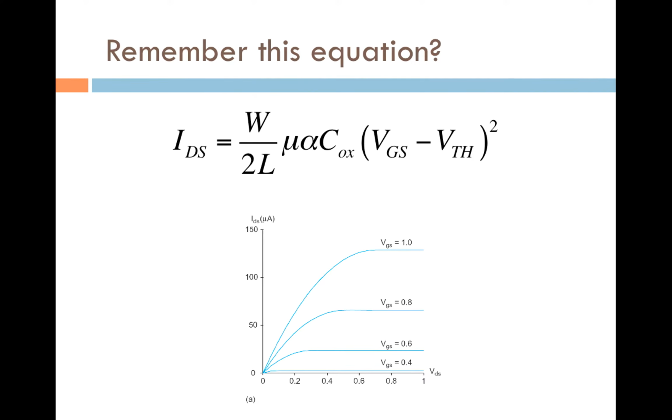You are surely familiar with this equation. It shows how the drain current of the MOS transistor has a quadratic dependence on the gate source voltage. As you can see in the graph, though VGS increases 0.2 volts each time, the saturation current increases quadratically as mentioned before. Well, we are sorry, but we have to tell you that...